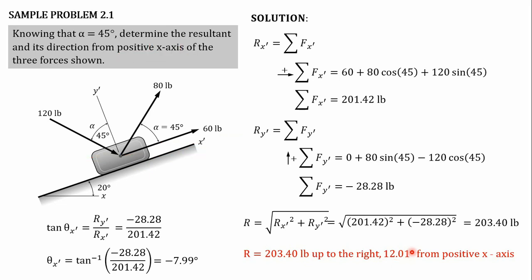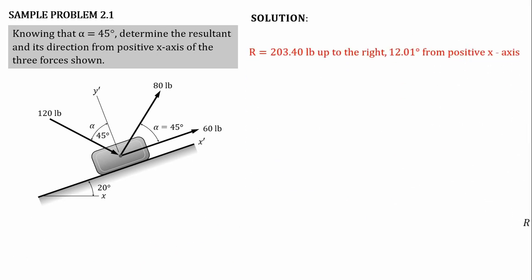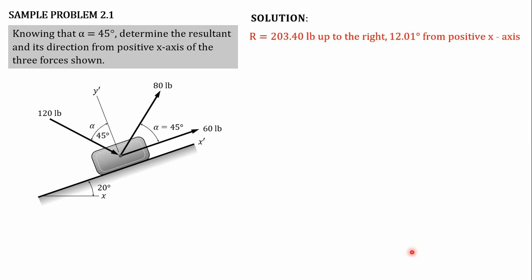How about if we solve this by force polygon? So, we can solve this by force polygon. Ito yung answer natin kanina, which is 203.40 pounds up to the right, 12.01 degrees from positive x-axis.